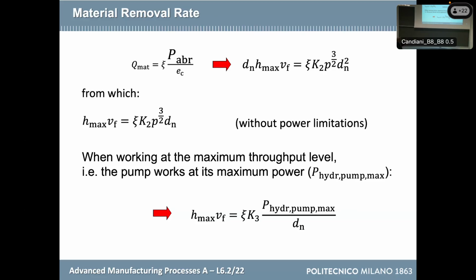And if I want to, let's say, obtain a smaller cut, even if powerful, I know that if I do that and I reduce the diameter, I will reduce the cutting performance. But the diameter of the orifice can be considered as a constant when you arrive here. So at the end, you can play, for sure, on the pressure. And instead, the discussions on the diameter of the orifice must be done before that.